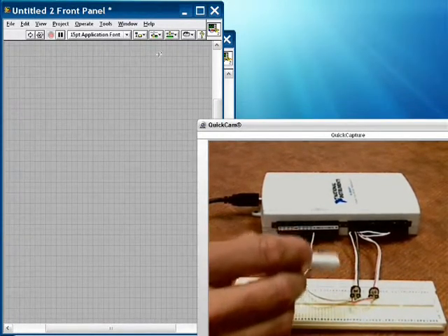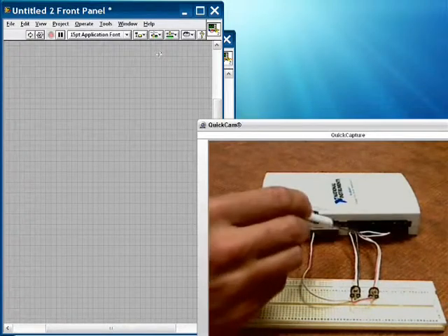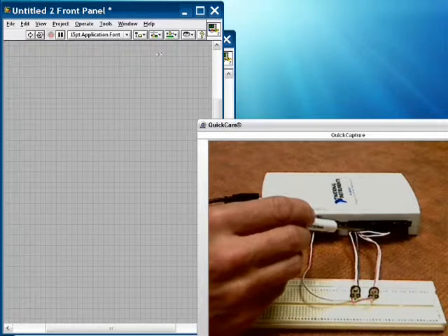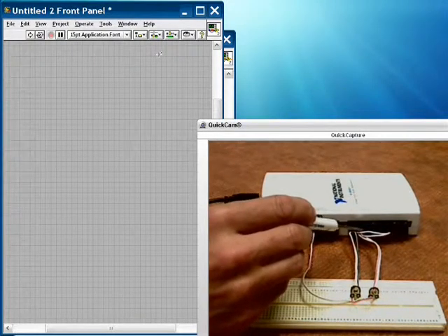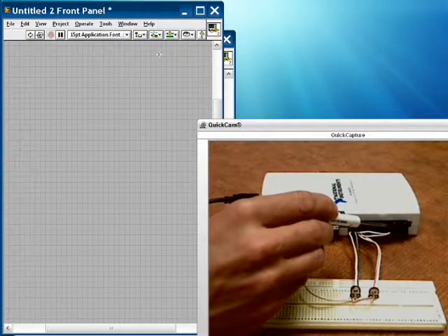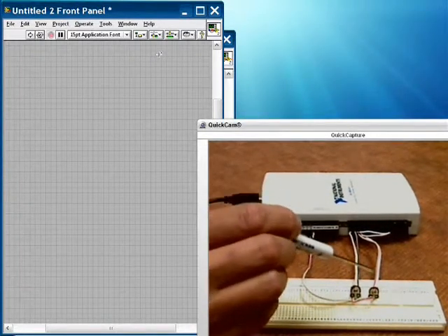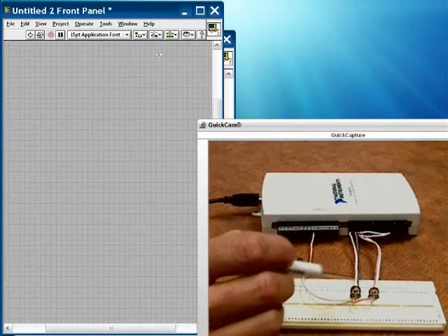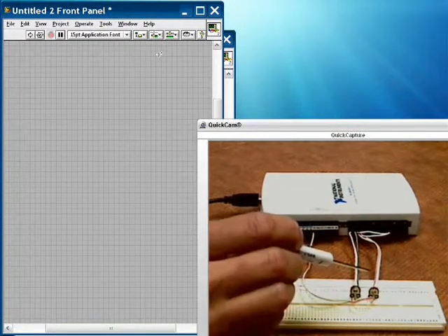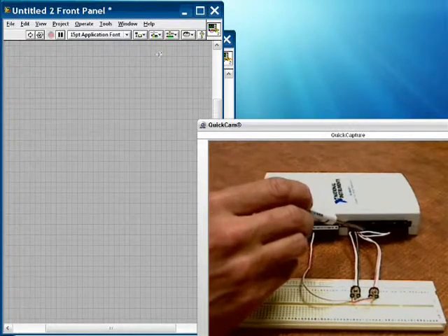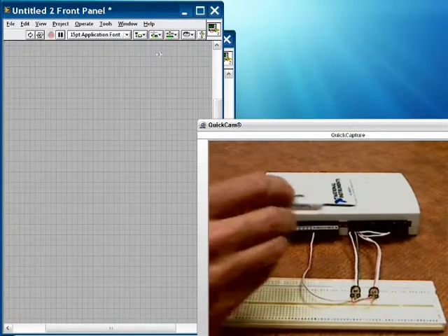Coming out of the potentiometers, we have the low side signals going back to the ground side or the low differential side of our analog input channels, and then we have those wired over here to the system ground of the USB-6211. In the center of the potentiometer, with a voltage that's going to vary with the motion on the potentiometers, we have a signal feeding right into our analog input channels 1 and 2. So this is our setup.